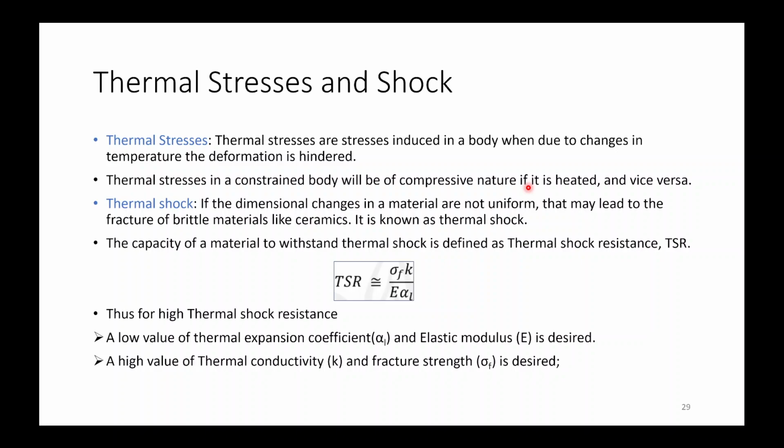So for example, if we kept a metal inside, restricted under certain constraints, when we are trying to heat it, the walls will be putting some compressive force on it, so there will be compressive type of stresses inside this material.